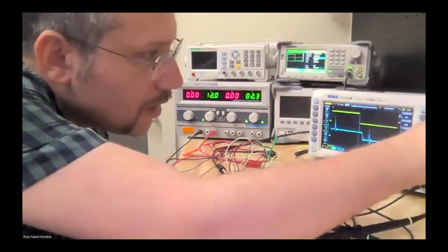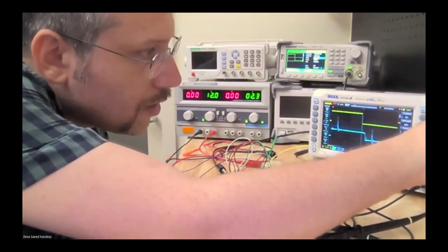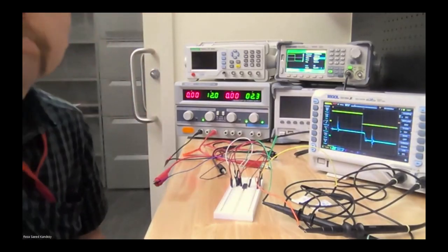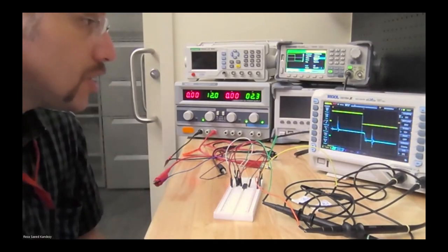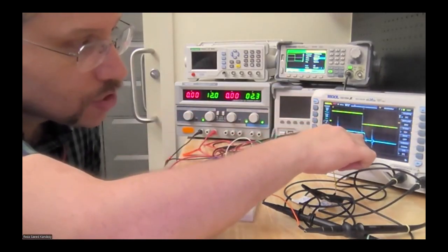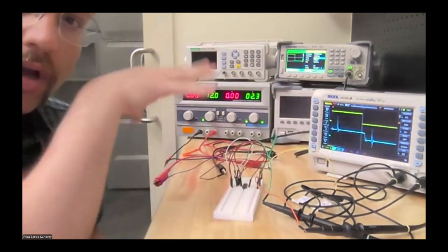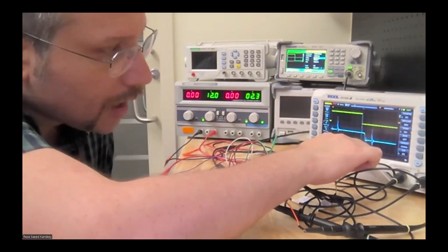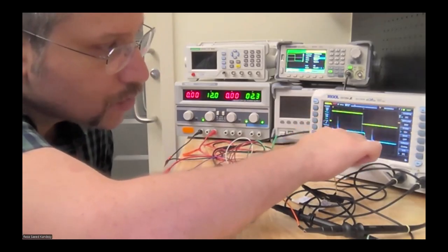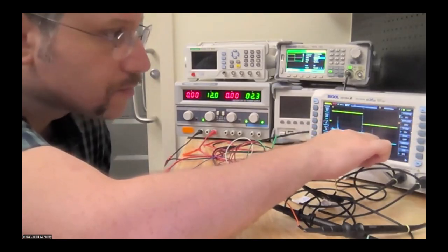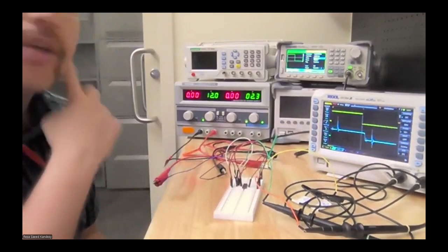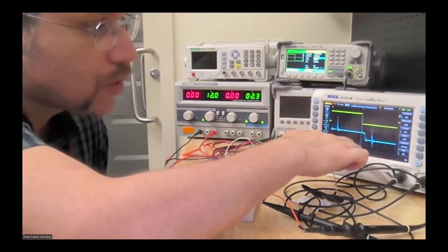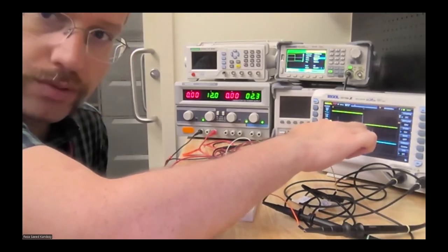Now, okay, you can see that still we don't have a precise, instant change in the output. And you can see there is a shift, there is a delay also. This also counts on the slew rate. So as you can see here, I have more duration of time from the edge of the input until the output gets to the final value. It is still 1.5 units of my volt division. I am still at 200 millivolts, so it's 300 millivolts.